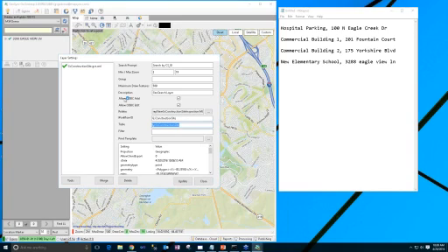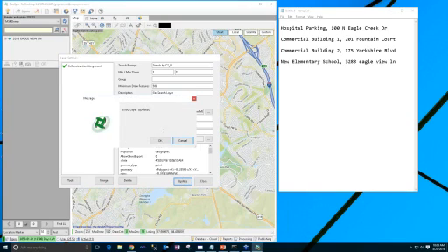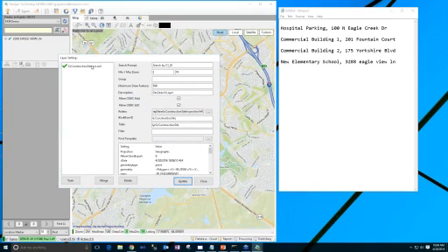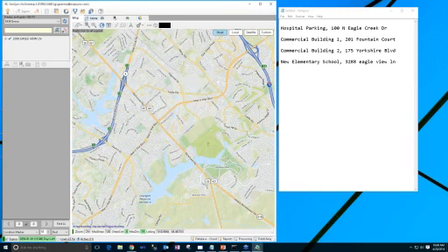The other thing that's necessary is that if we want to be able to add features, then both the Allow ODBC Add and Allow ODBC Edit, both of these items need to be checked for that particular layer. And they are. If they're not checked, then you need to check them and then click Update, and that'll save those settings for this particular workflow layer and then close. Let's go back and open up our GS construction site layer again.